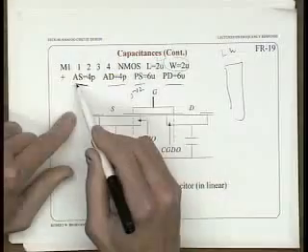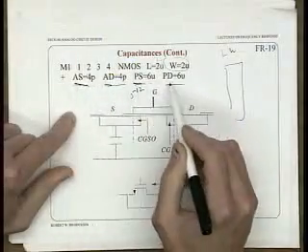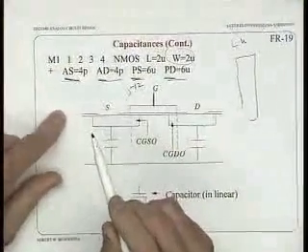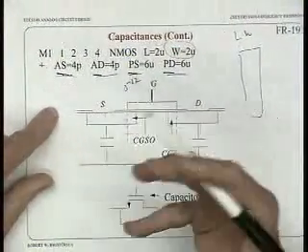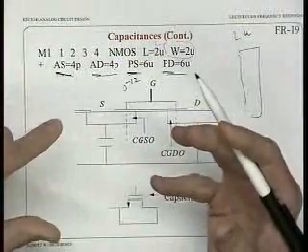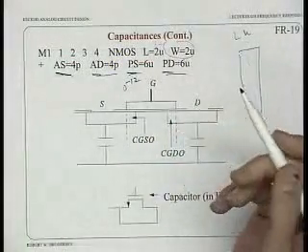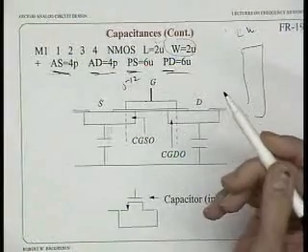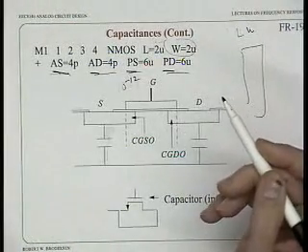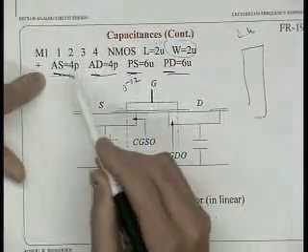When you put in your transistors, you've got to put in, I think I did this in the notes. Here it is, right here. I'm pretty sure it's the same syntax as this. You need to put in area of the source, area of the drain, perimeter of the source, and perimeter of the drain. If you don't put those numbers in, it's like your transistor doesn't have any source or drain, or there's some very small default value. And so your transistors will work very, very fast. So you have to include these values here.